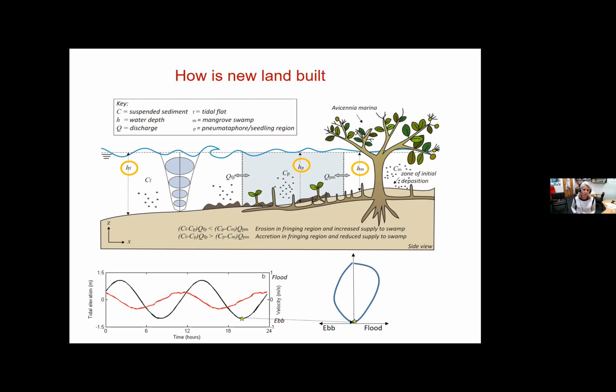And the advantage of plotting like this, as a tidal stage plot, is we can instantly see if the right-hand side of that plot is greater than the left-hand side, which will mean the flooding currents are greater than the ebbing currents. And we can also see when that occurs. Does it occur closer to high tide, or does it occur closer to low tide? So I just plotted that out to get you used to looking at a tidal stage plot, because I use them a lot.